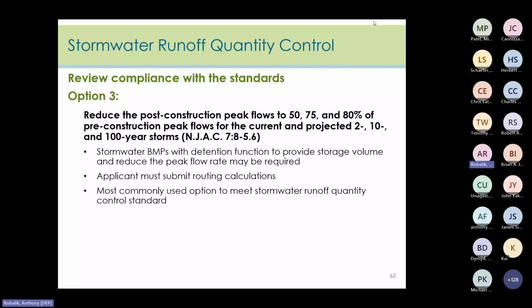This option requires use of green infrastructure stormwater BMPs that make use of a detention function and an outlet control structure to attenuate the flow.